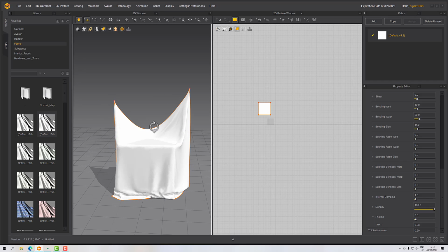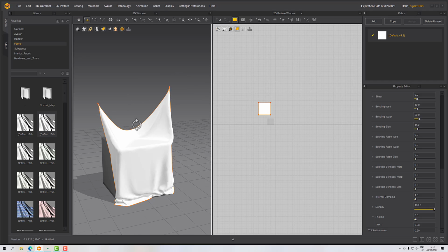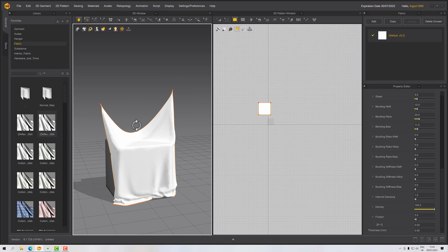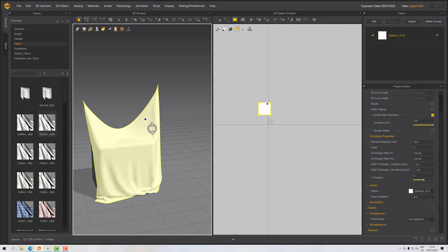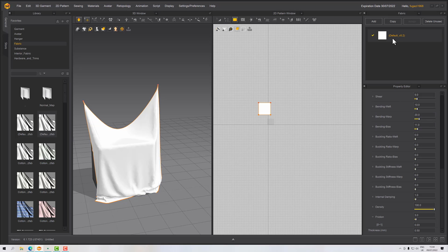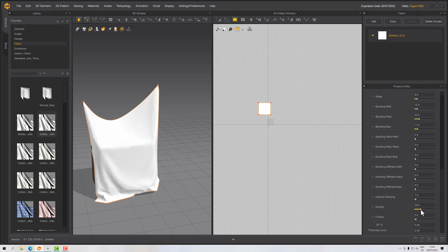You'll see it's really draping, it's really pulling against itself, because it's much heavier. It's reaching the ground. We've got really stretched bits up here. So it can be really useful to amend how things are working. And I've used it in skirts essentially. If I want a much heavier skirt, then I increase the intensity, and it will pull the skirt down much further, and give me a really nice drape.